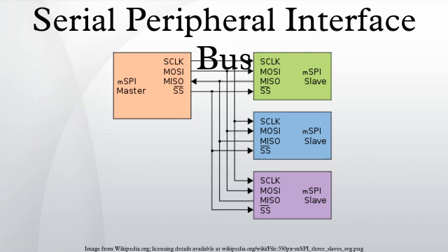ESPI slaves are allowed to use the ESPI master as a proxy to perform flash operations on a standard SPI flash memory slave on behalf of the requesting ESPI slave. 64-bit memory addressing is also added, but is only permitted when there is no equivalent 32-bit address.